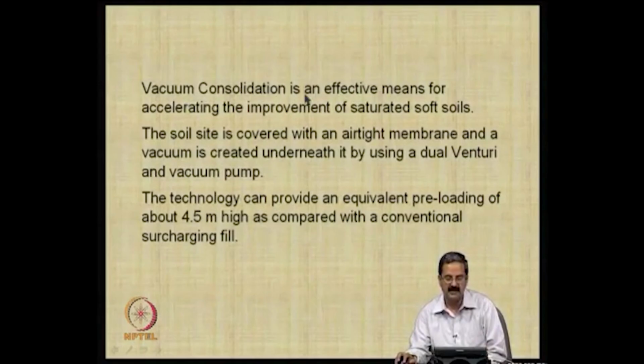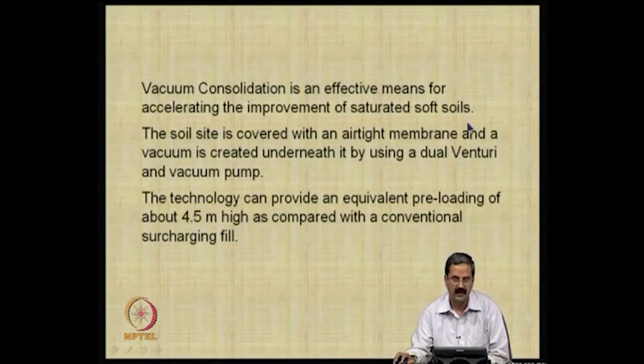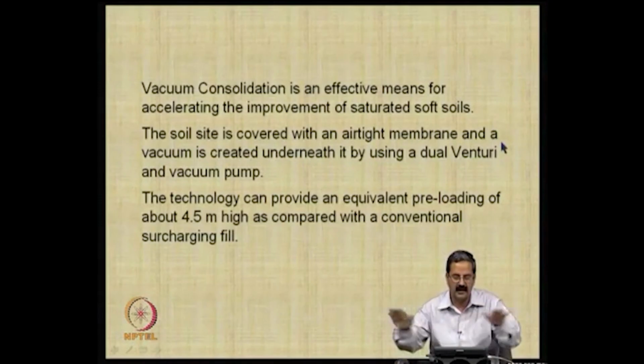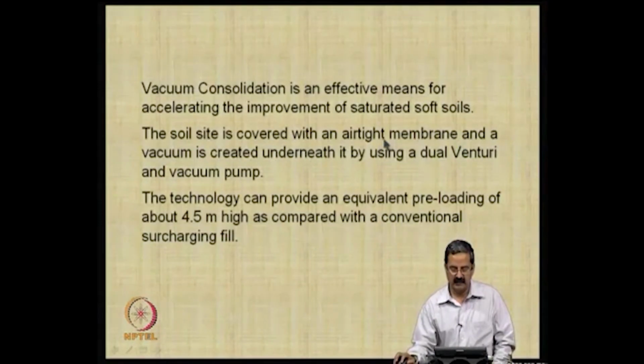So it is an effective means of consolidating or accelerating the improvement of saturated soft soils. The site is completely covered with an airtight membrane, and a vacuum is created underneath it using a dual Venturi vacuum pump. There is a pumping system here. The technology can provide an equivalent preloading of 4.5 meters height, compared to conventional surcharge fill.